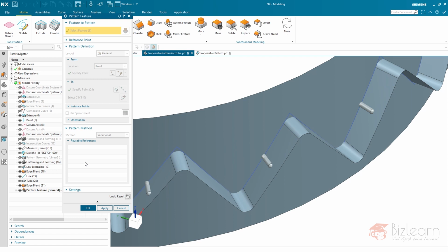If you reuse this edge, the slot is still going to follow the curve when being patterned, and the length thereby is different. If you don't reuse it, it's going to be straightforward. But the length of the line is defined differently.